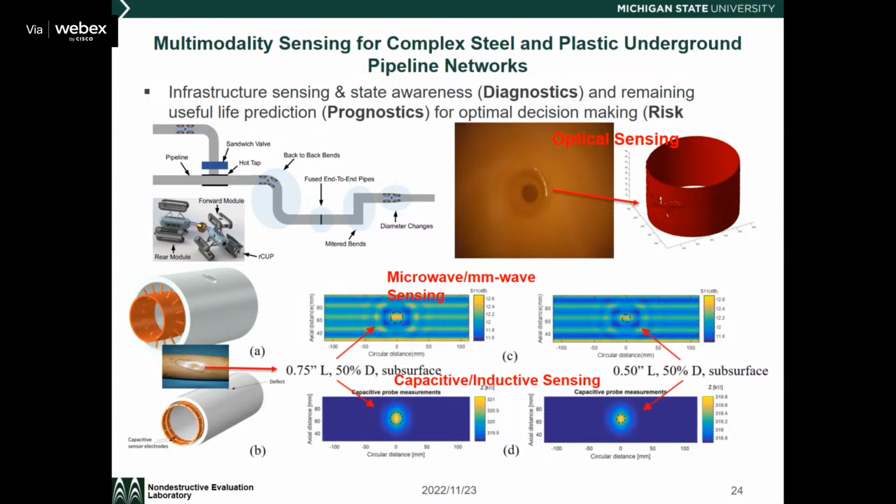And this is called an underground pipeline network. It can be either steel or plastic. We typically focus on the distribution pipeline network. Distribution means the diameter of a pipe is smaller compared to transmission. So this becomes an unpiggable problem. I don't know if you guys are familiar with pig or piggable. Pig is not the animal. Pig is called pipeline inspection gauge, where you can see here we can have a robot for the unpiggable case because it's very complex and small diameter.